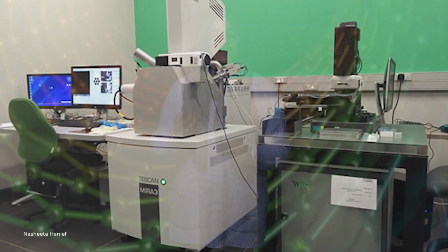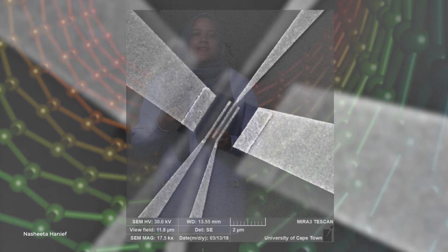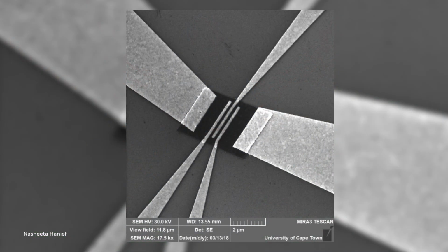In order to create these quantum electron pumping devices, we use a microfabrication technique that is available at the electron microscope unit at UCT. The fabrication technique is electron beam lithography. It forms part of the advanced scanning electron microscopy techniques wherein the beam scans the resist-covered sample according to a pattern generator. To fabricate the devices, we locate the microstructure, the nanostructure, on the surface of the semiconductor substrate and pattern the gate barriers to confine the space for electrons to be transported. The resultant devices are coated with gold to form the gate barriers across the nanostructured semiconductor.